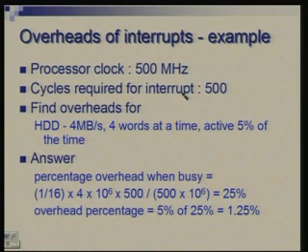Now, if the disk drive was always active, then things are going to be as bad as polling. You will get continuous interrupts. In fact, it would be worse because every time there is an interrupt, the overhead is larger. But the reality is that the device, the hard disk drive in this particular case, will not necessarily be always active.